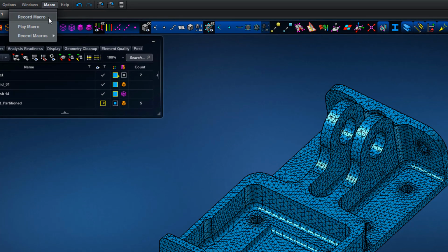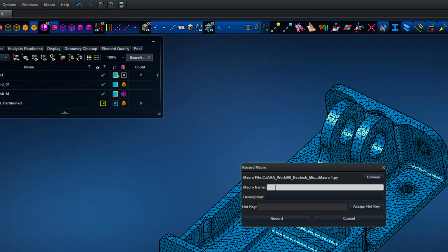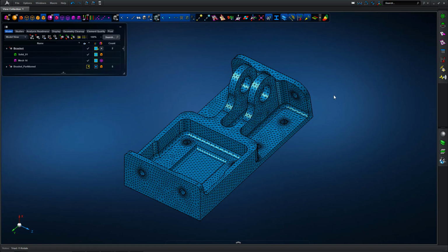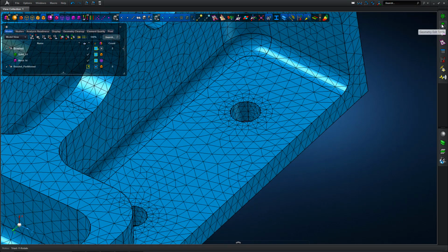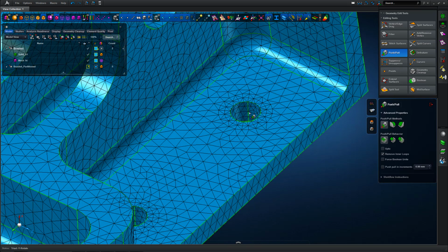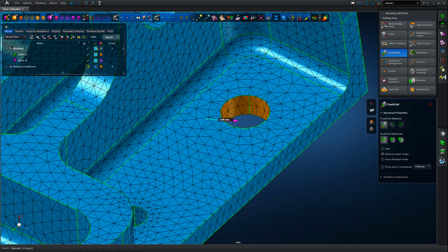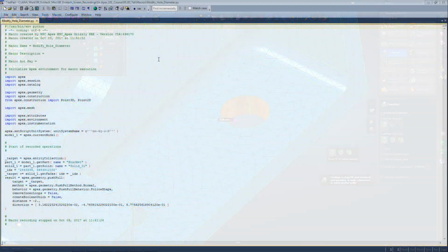We can do it on a manual approach, or we can record a macro to automate the full modification that we want to make and store it in a macro. Here we've got lots of holes, a typical aerospace application where we may have a Mark II geometry which is based on a different fastener size, a different hole diameter size. Again, we're simply recording a macro, highlighting the push-pull or hole increase that we're interested in, and then we can stop that macro and go into the macro settings.